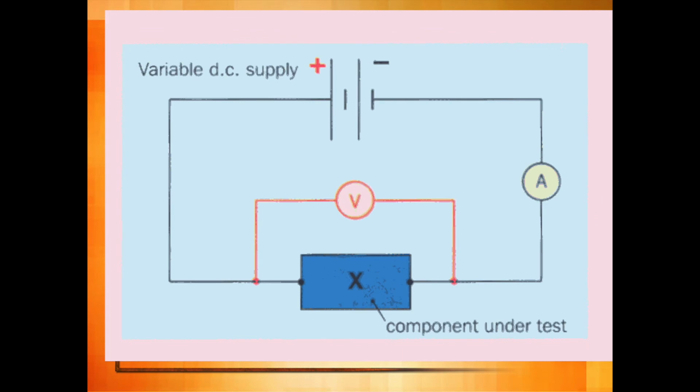So in order to take the measurements that we would be looking for here, we would use a voltmeter and an ammeter. A voltmeter needs to be able to measure the amount of voltage drop across a given component. And so in order for it to have the same voltage drop, it's hooked up in parallel to that component. Because it's hooked up in parallel, we want to have an incredibly high resistance on that voltmeter, so a teeny tiny amount of current goes through it, so much so that it doesn't affect the rest of the circuit.